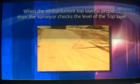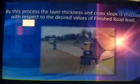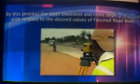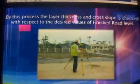When the embankment top layer is prepared, then the surveyor checks the level of the top layer. By this process, the layer thickness and cross slope is checked with respect to the desired values of finished road level.